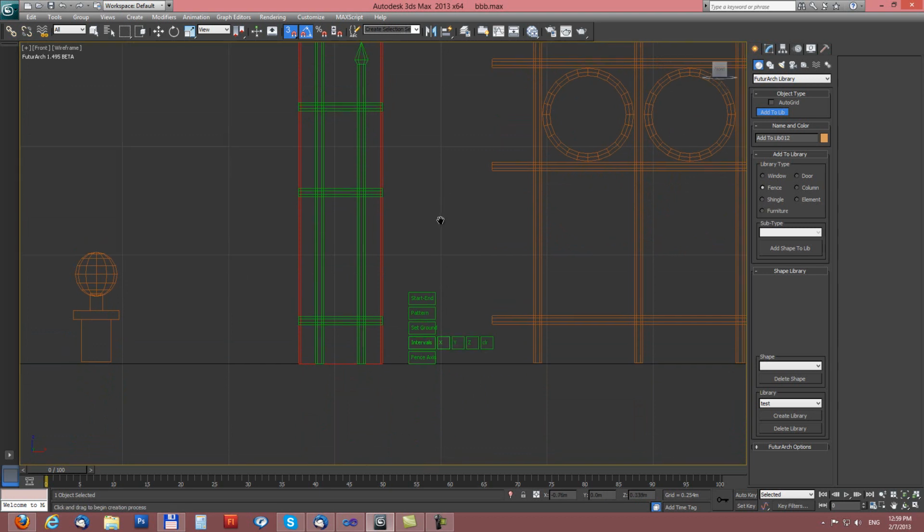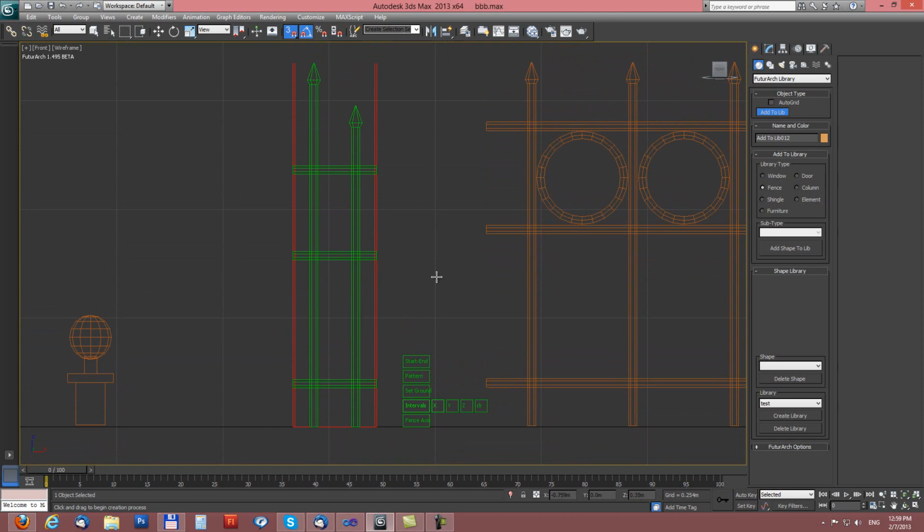Fixed intervals, with these intervals we can set how geometry will be stretched. So in this case we just use the intervals along y-axis, so from position here to the top this part will be fixed, and also from position here to the bottom this part will be fixed, and here in the middle it will be stretched along y-axis, because we will be changing only height of this fence, and we want to have some parts be fixed.